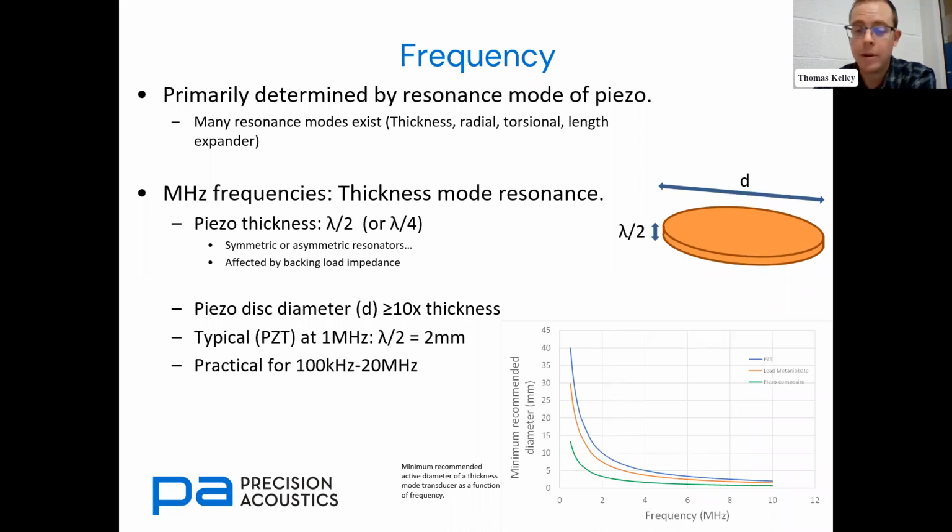If we had a low element count, for example only 4 or 8 elements, then it's a little impractical, but it's still within the realms of possibility to acquire 4 or 8 discrete laboratory amplifiers, send the signal to each of them and control the inputs to the amplifiers through some sort of software means. But if you're looking at high element count arrays, then that approach becomes a lot more impractical. If that helps to answer the question.